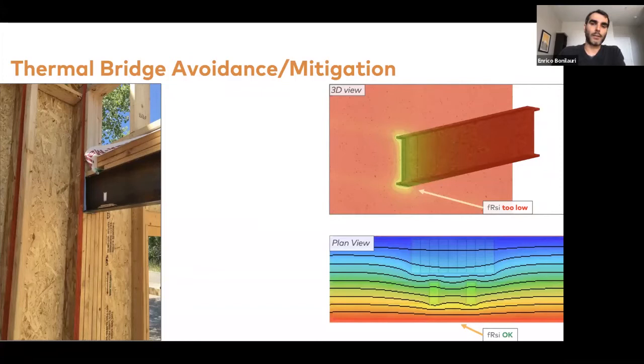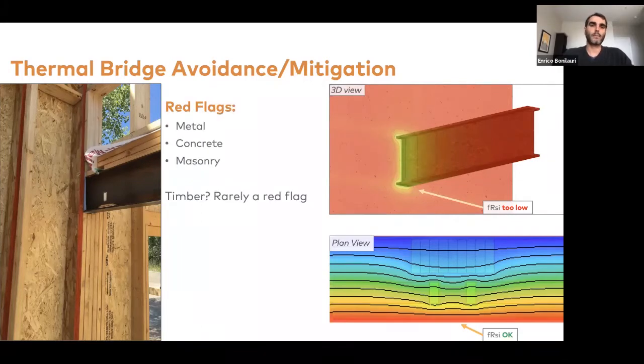So as a designer, you can decide not to address this kind of thermal bridge because it will only impact the energy performance, but overall the building may be okay. Again, the determining factor, in my opinion, is to avoid mold and condensation as a first priority. No net zero or green building is efficient or green if the indoor environment is not healthy. So avoiding mold and condensation needs to be a very high priority for everyone.